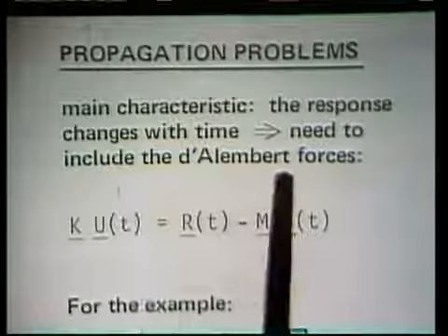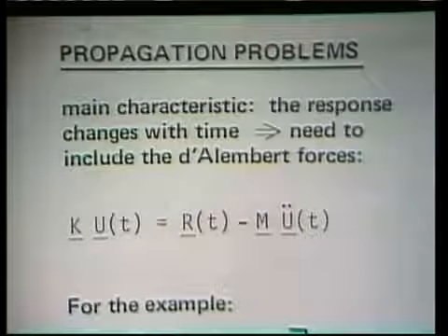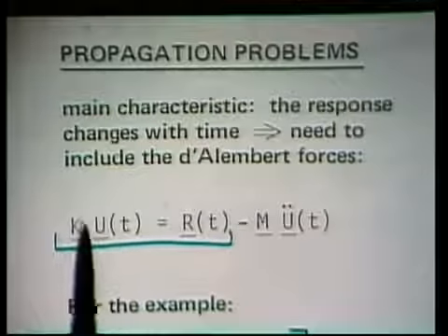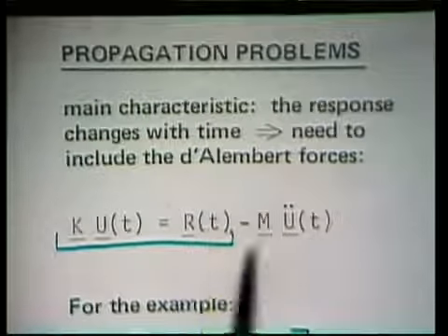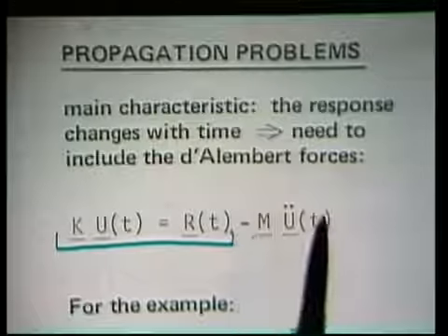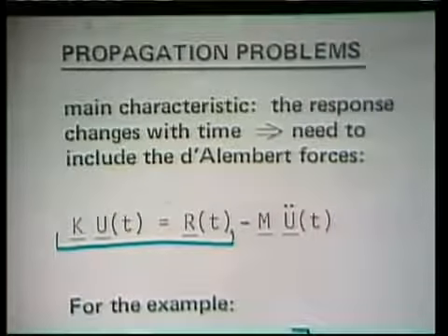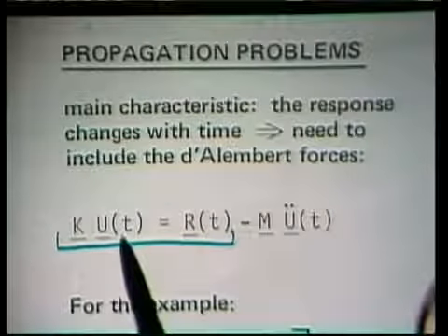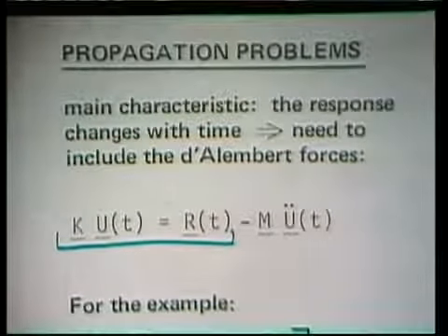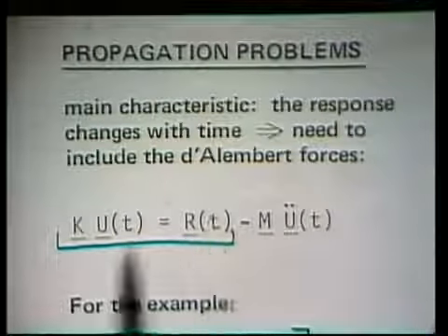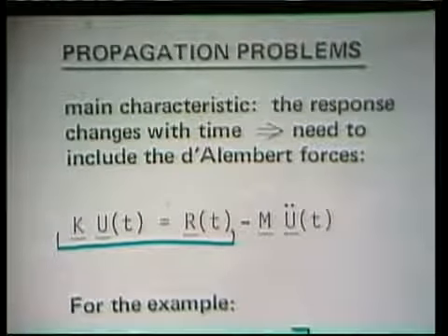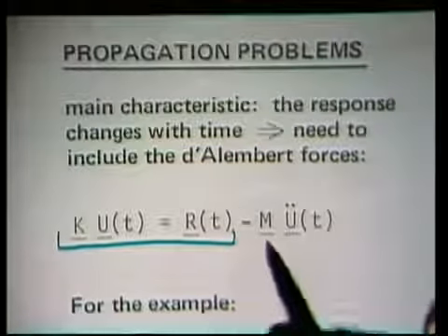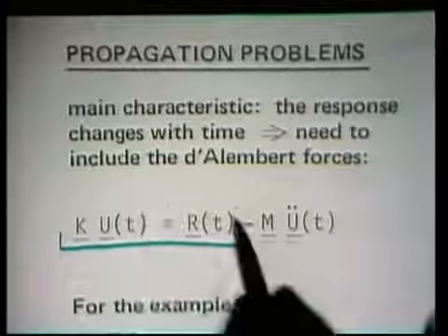The main characteristics of propagation problems are that the response changes with time. Therefore, we need to include the D'Alembert forces. Basically what we are saying then is that we are looking at static equilibrium as a function of time, but also taking into account the D'Alembert forces. And that together then makes it a dynamic problem.